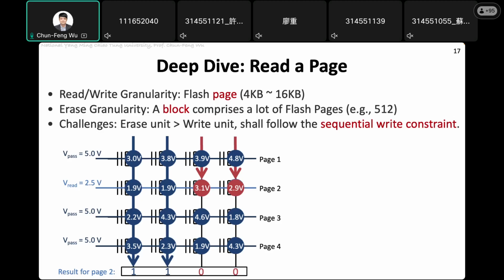If you program one time and then program a second time, the electrons are already inside, so you have no chance to do the programming. So each time you do a write, you first need to do the erase, to let the page go back to the original state, where there is nothing inside the floating gate for those cells.